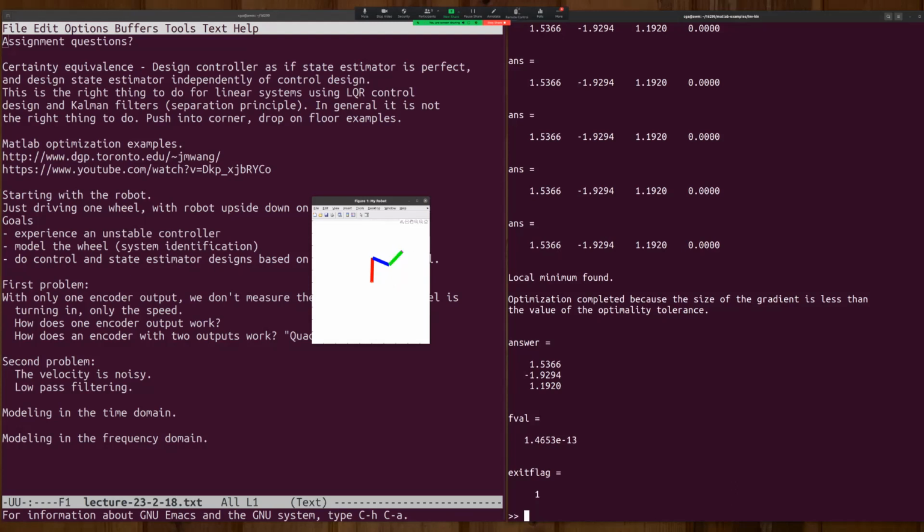That would be the angle of the shoulder plus the angle of the first elbow. Typically we want to make things always positive, and the usual thing to do is square it. So if we squared the sum of the shoulder angle and first elbow angle, and penalize that as well, then we're probably going to get a unique answer out of this thing. And so that's a great answer.